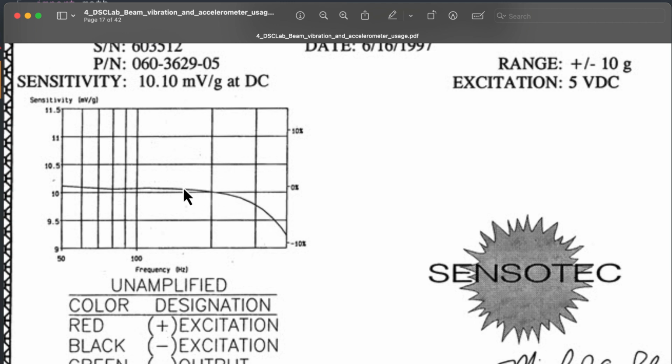So where you want to use this accelerometer, and that's what the frequency response tells you in this context, is within this 200 hertz bandwidth. So when you look at this accelerometer, they would tell you, hey, the bandwidth of this device is 200 hertz. Where that specification comes from is from a frequency response function. I'll talk more about some other applications in the related video on experimental measurement.